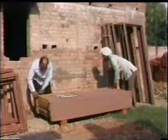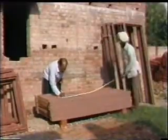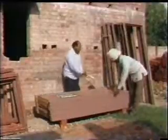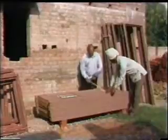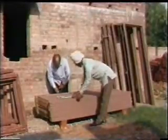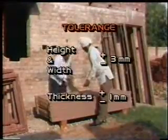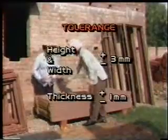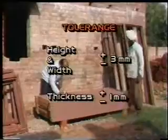Dimensional checks for height, width, thickness, and sizes of stiles, rails, etc. are carried out and matched with specifications. The maximum permissible tolerances for height and width are plus minus 3 millimeter and for thickness plus minus 1 millimeter.